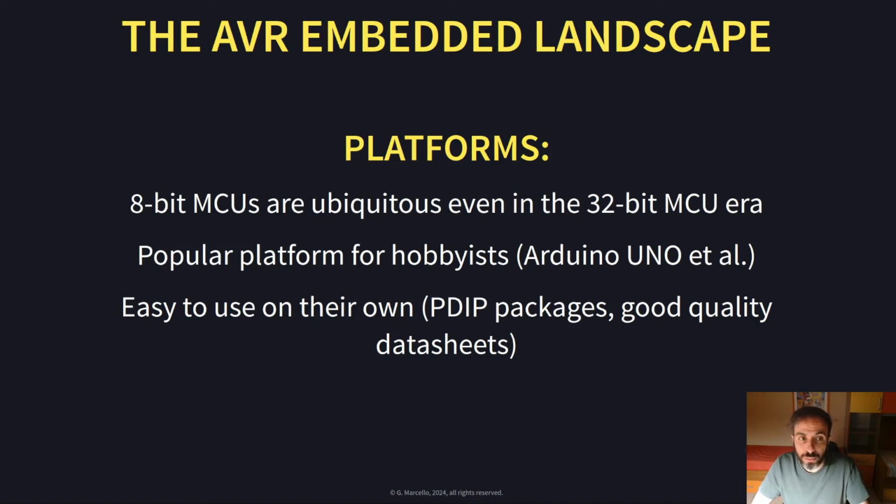They're also a really popular platform for hobbyists, mainly due to the legacy of the Arduino Uno, which is probably the most famous board with a microcontroller on it, and it mounts an ATmega328P, at least up until revision 4, I think. Also, these AVR chips are quite easy to use on their own with a breadboard, for example, because a lot of the time they come in through-hole PDIP packages, which are really easy to use.